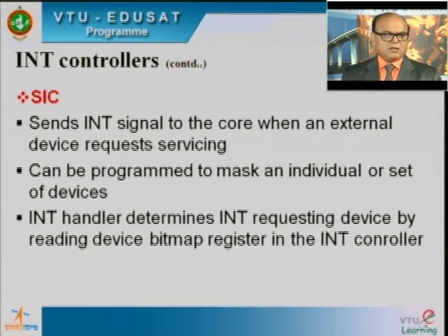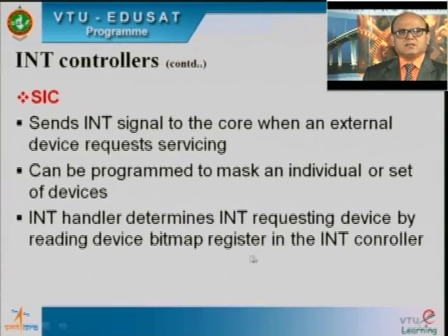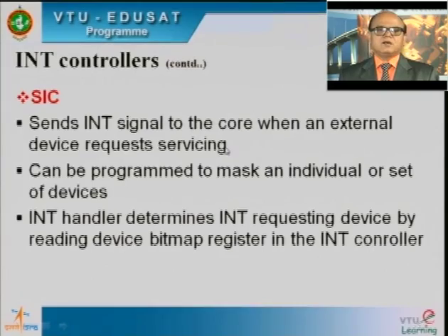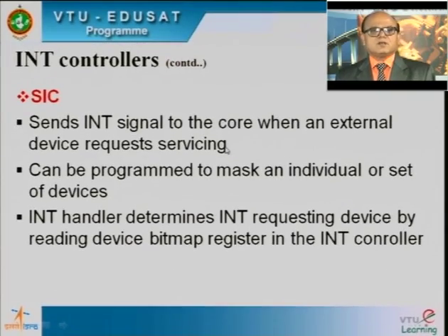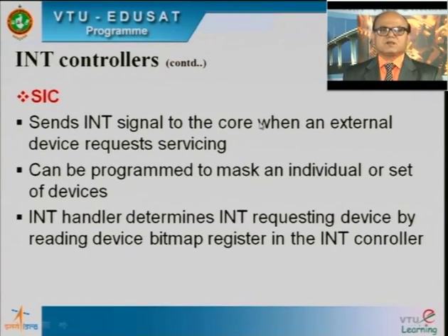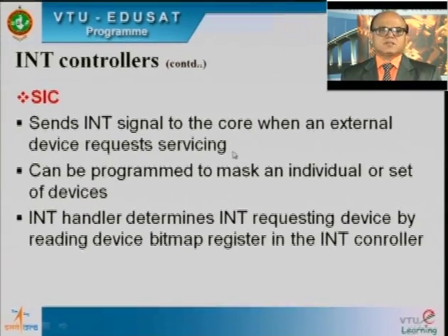Coming to the SIC, the standard interrupt controller, it sends an interrupt signal to the core when an external device requests servicing. When an external device requests execution of the interrupt handler, the controller will send a signal to the core indicating that a specific peripheral device requires a handler to be executed.